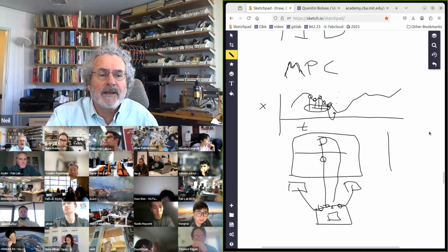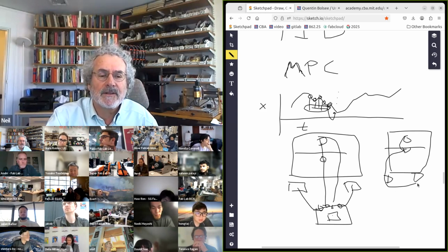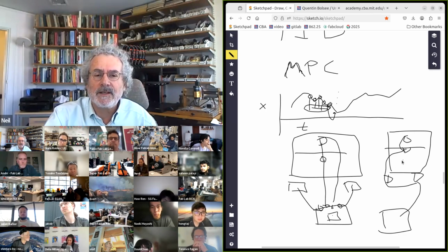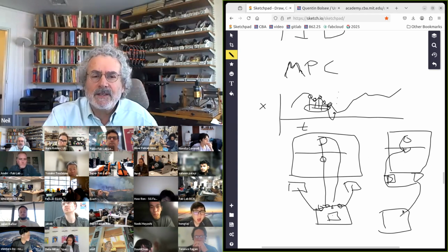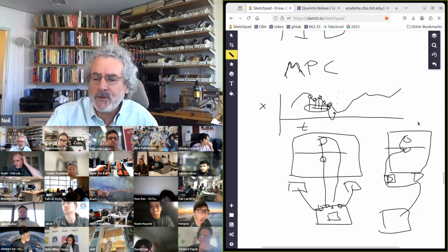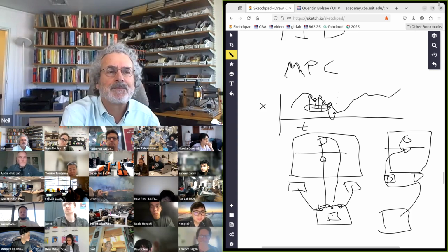So the alternative way to do this is to take all the degrees of freedom in the machine and just put them on a network like we covered last week. And so you don't have a controller in the machine at all. All a motor knows how to do is make a step, but you network the machine, and then in software, you use the network to tell it what to do.